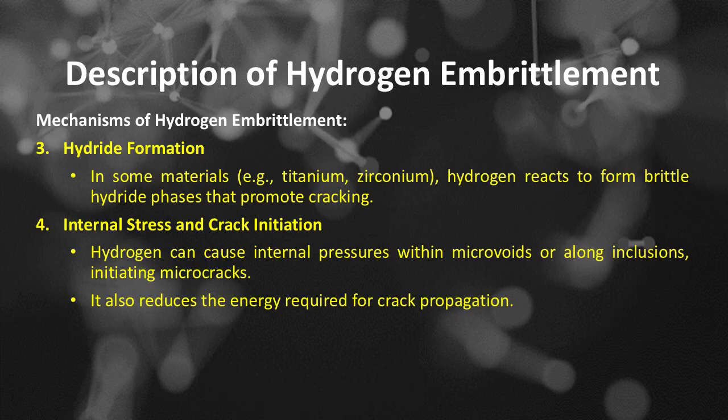Number 4, internal stress and crack initiation. Hydrogen can cause internal pressures within microvoids or along inclusions, initiating microcracks. It also reduces the energy required for crack propagation.